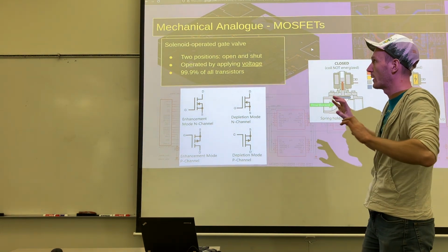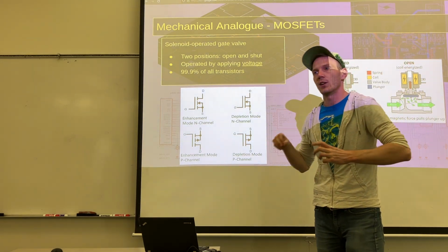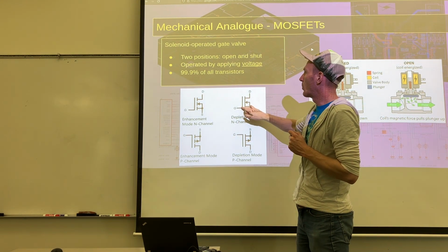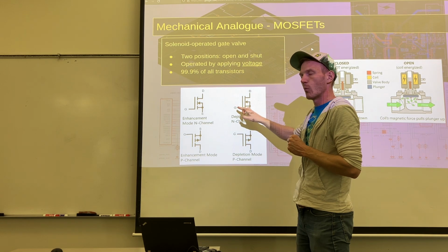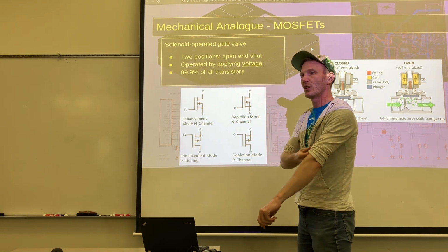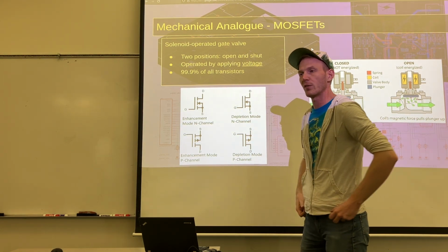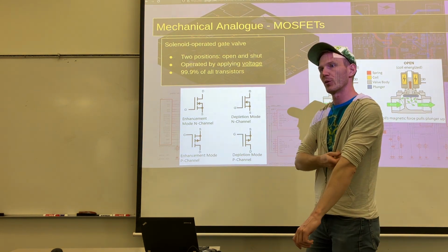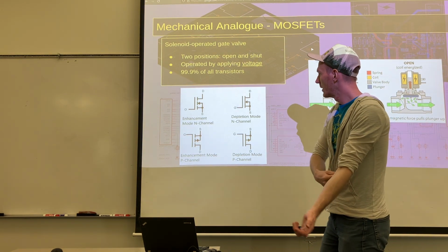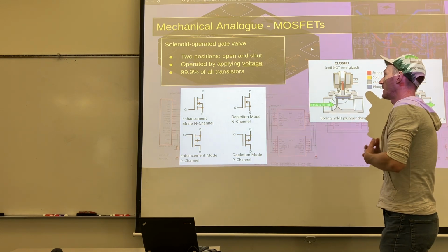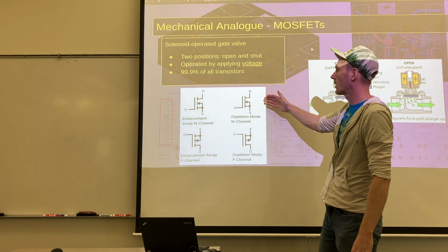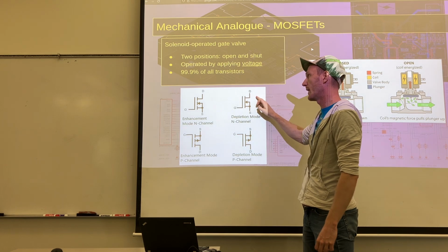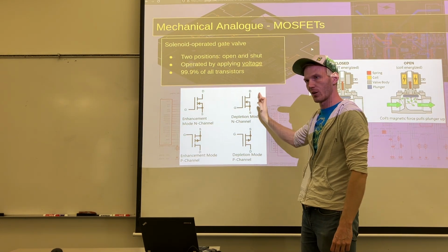So what you should take away from field effect is there is no path for current from this side. And what that means is this is purely voltage controlled. The presence of the voltage creates an electrical field which operates this. Going back to this being a gate valve, when voltage is applied to this, it permits current flow here.